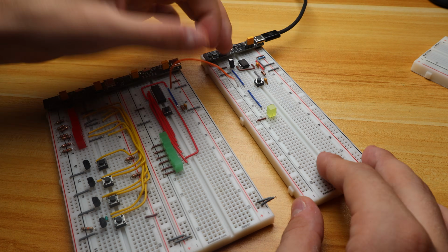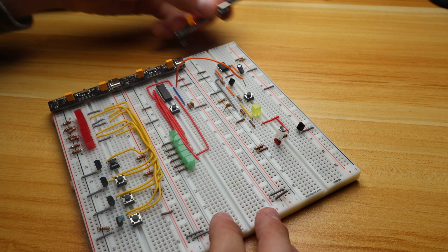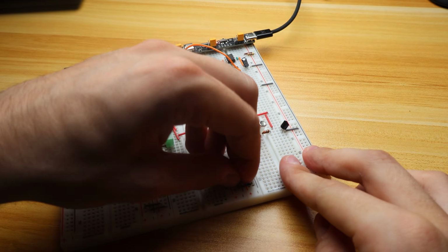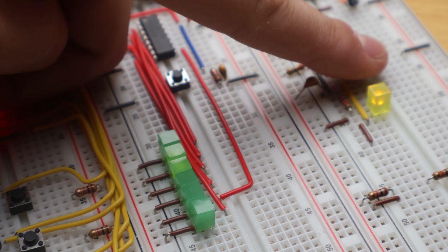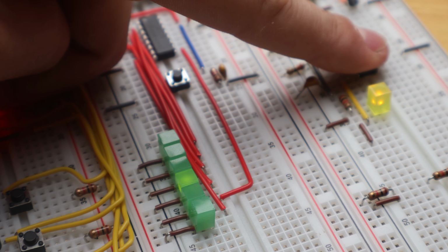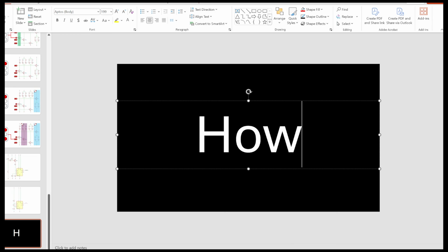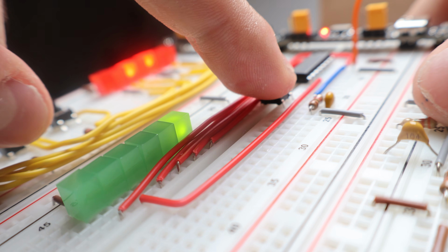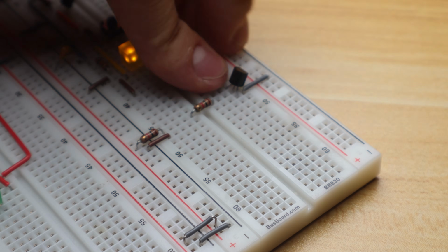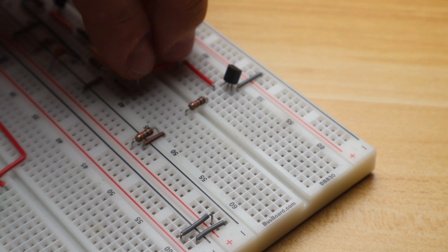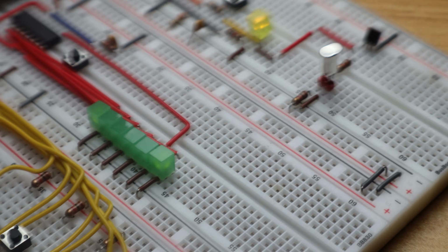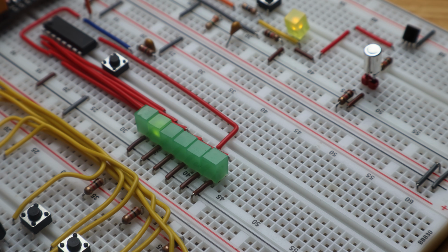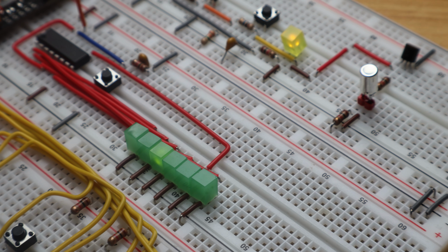Anyways, after building and optimizing the timing, I removed my old 555 timer and added a new one. What happens now is after I press a button, it loops the decade counter, but if you watch closely, after I release the button, it takes a few more steps to roll. However, pressing a button isn't very dice-like, so I made a small adjustment to the circuit and added a vibration switch, which required only a single transistor to invert the logic. Now I could shake my breadboard, which turned on the 555, loop through the decade counter, loop through the dice, and after stopping, it will roll just a bit more.